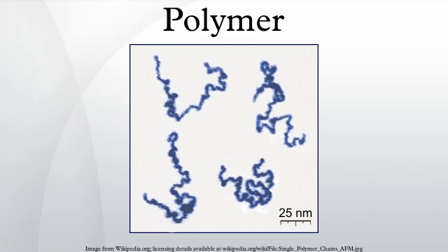Traces of chlorine in the water supply attacked vulnerable polymers in the plastic plumbing, a problem which occurs faster if any of the parts have been poorly extruded or injection molded. Attack of the acetal joint occurred because of faulty molding, leading to cracking along the threads of the fitting, which is a serious stress concentration. Polymer oxidation has caused accidents involving medical devices.